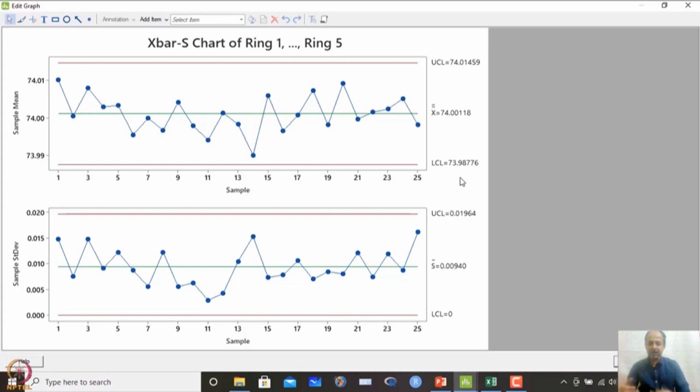Okay. So, the gap is very small. In that case we cannot round up the figures over here, because it is very sensitive and the data are very close over here. When the variation in the data is less, we will find that the stretch between the upper limit line and lower limit line is also close basically. And that is also true for range or standard deviation if the data is not varying much.